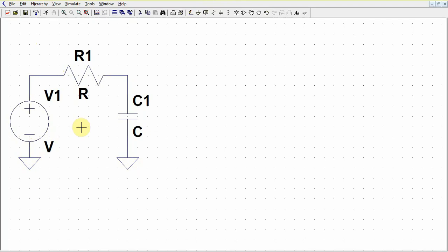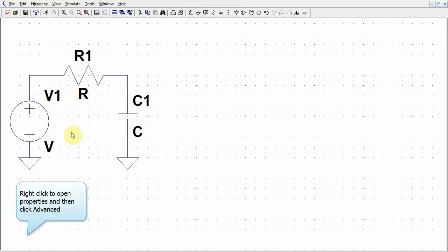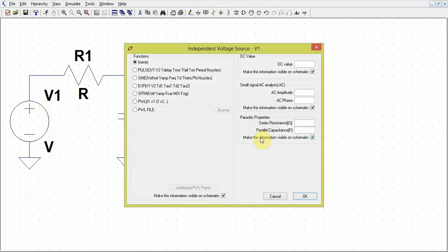simulate a frequency sweep, meaning we can get this voltage source to go from a very low frequency to a very high frequency, and we can define our start and stop frequencies, which I will show you right now. Exactly. So we want to do AC small signal analysis. Now here you can leave it as a DC value, or you could leave it as small signal AC analysis.